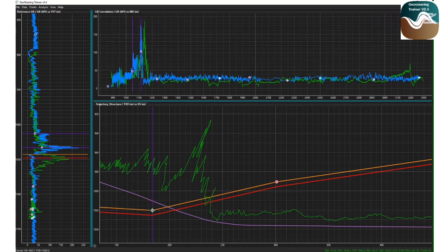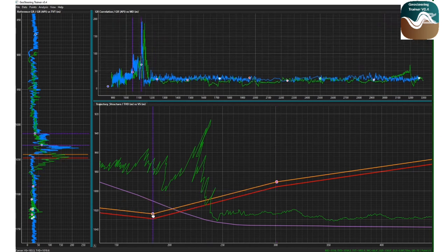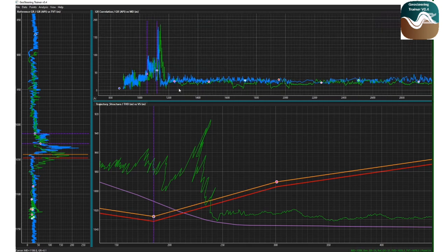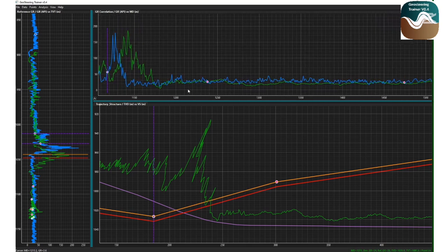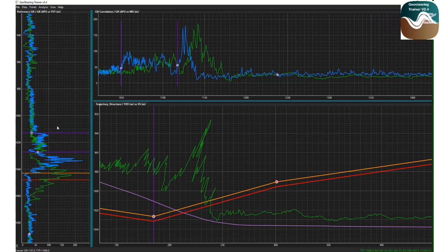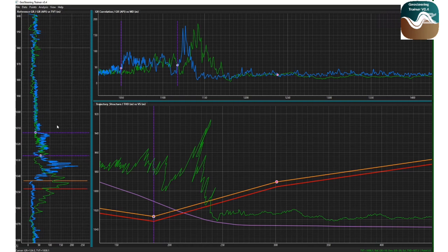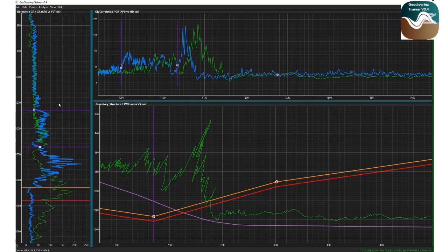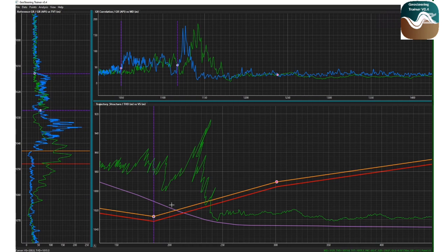Now comes the most critical part of the workflow: defining reservoir boundaries. The application uses an intuitive double-click interface to add boundary points directly on the trajectory plot. Each double-click adds a new boundary point that represents where the wellbore intersects the reservoir top. As you add points, the application automatically numbers them from left to right based on measured depth, making it easy to track your interpretation progress.